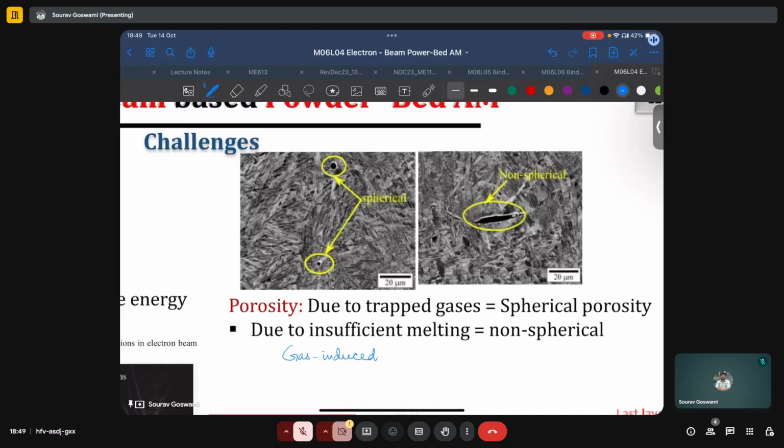This gas will get liberated from the solid and keep accumulating in the liquid until finally it will exceed the solubility of the liquid also, and then form these spheres of gas. Later, when the gas is released from the system, these sphere-like voids are left behind, and these are called gas-induced porosities. They will typically be perfectly spherical, and even their sizes will be relatively small.